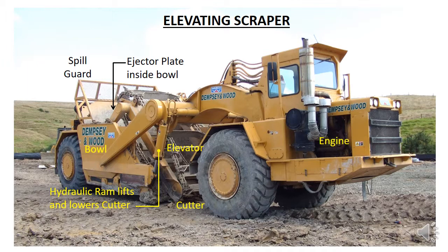So cycle time is the time it takes to load, travel, and lay the material, and then return back to loading again. So they're able to do this faster than other options when the haul distance is between 400 and 2,000 meters. For longer hauls, trucks loaded by excavators tend to be more efficient as they can travel faster. So what they lose in the loading and dumping times, they make up for in the travel time.